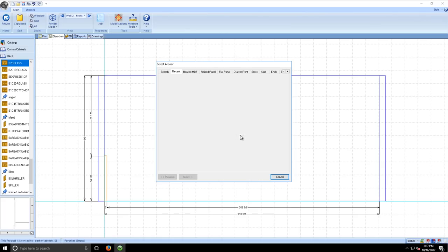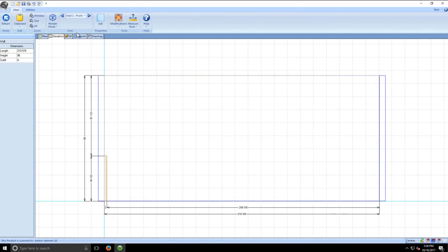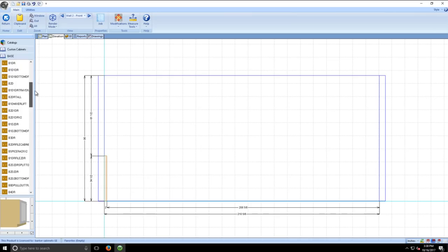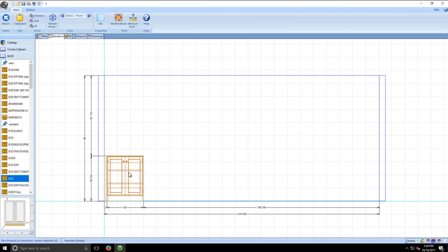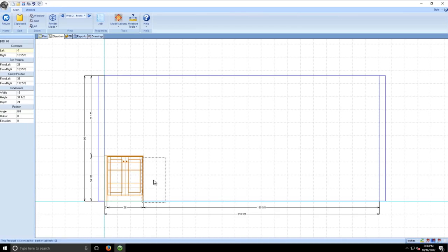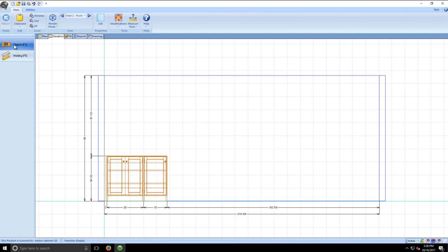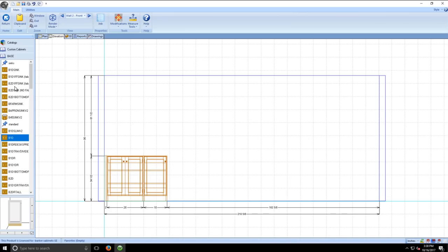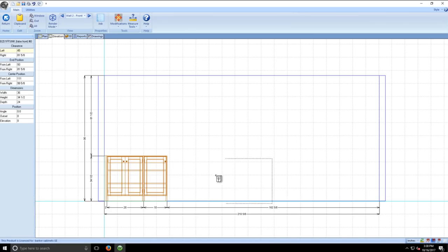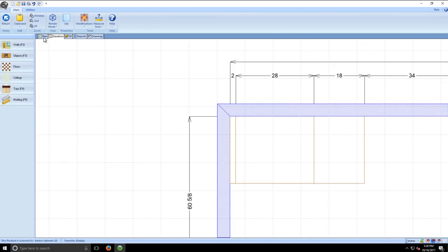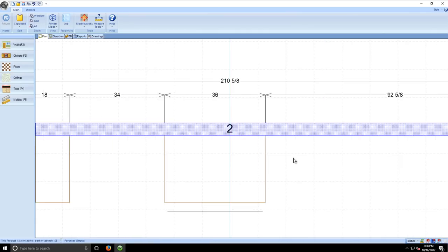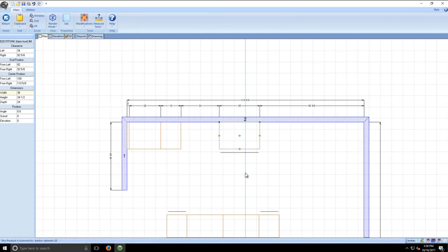Yeah, let's not use glass cabinet. Nope. Okay, so let's just add in some 1-door and 2-door base cabinets. There we go. 2-door, 1-door. Again, I'm gonna let you guys deal with it. Objects. I'm gonna go up here. I'm just gonna put in a 2-door, 1 false front sink cabinet. That's pretty cool, right there. When you're doing those, always make them 36 inches wide. That's really just more of a tutorial. I just want to show you guys how to use Cabinet Vision in this one.